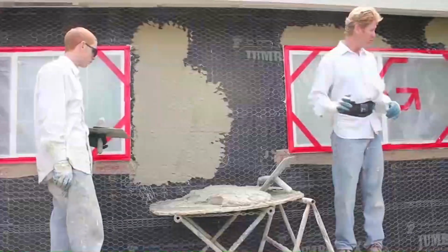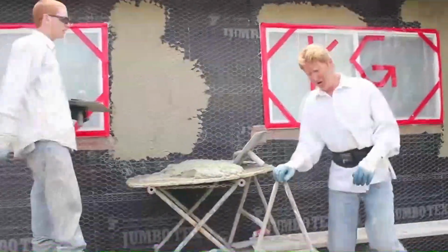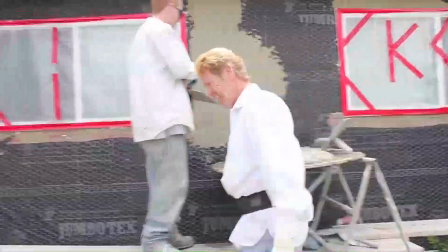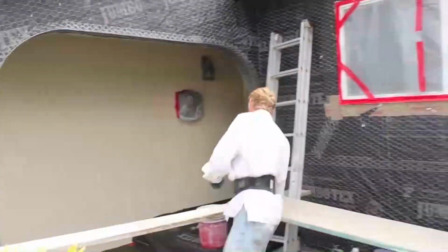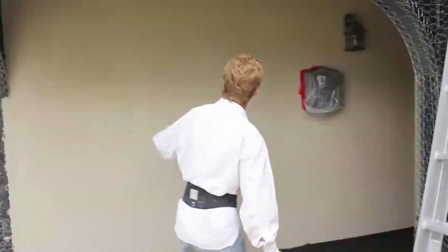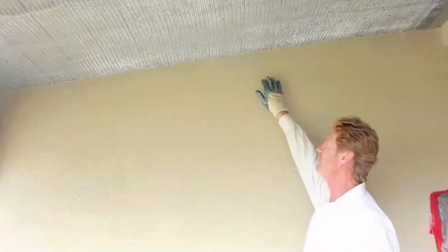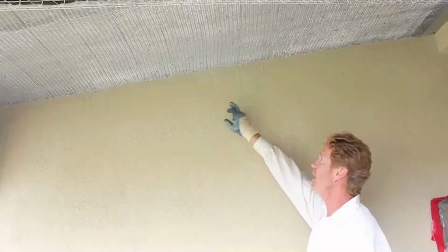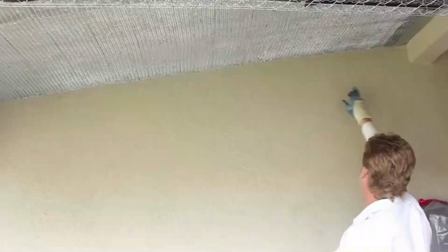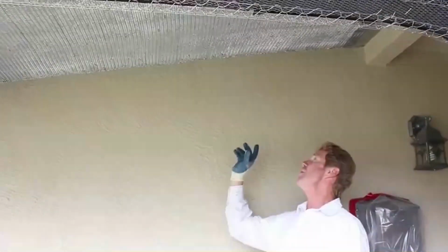I want to show you a few things. Great lath job. First of all, over here we'll point out a couple of little minor things that are kind of important. We've got a soffit mesh going into a wall that is not broken out. Well, we don't need to break it out. That blue stuff is called Weldcrete. It's all the way around the perimeters where we don't have wire tie-in, so we don't get any hairline cracks there when this all sets.